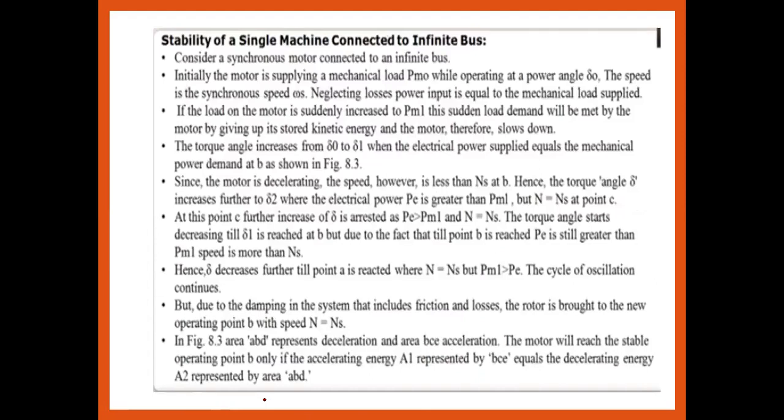Let us discuss an example of the stability of a single machine infinite bus system, for which we will use the equal area criteria. Just consider a synchronous machine that is connected to the infinite bus. Initially the motor is supplying the mechanical load, that is PM0, the initial mechanical input, while operating at an angle del 0. So PM0 is obtained at del 0.